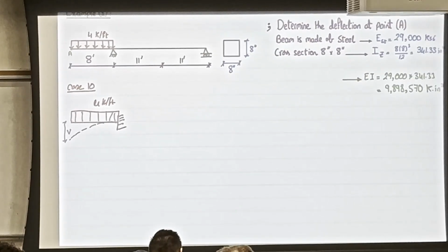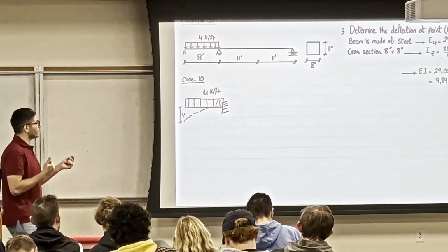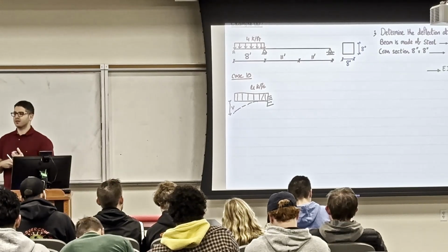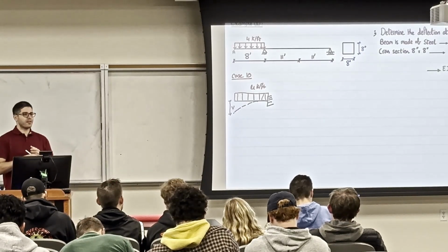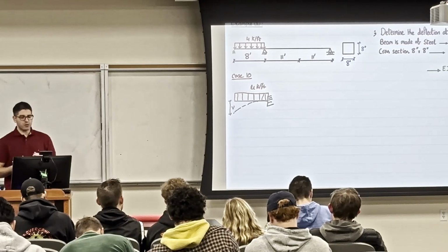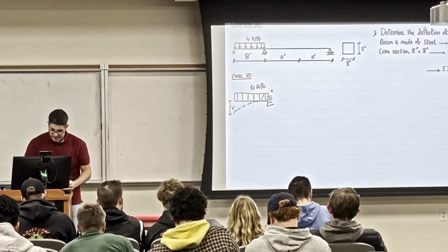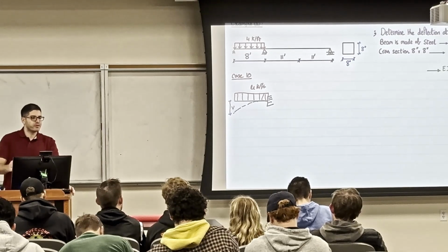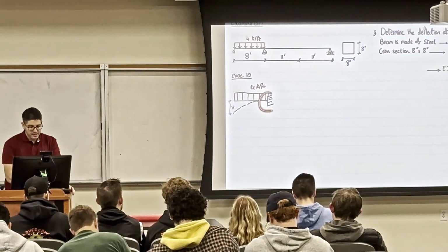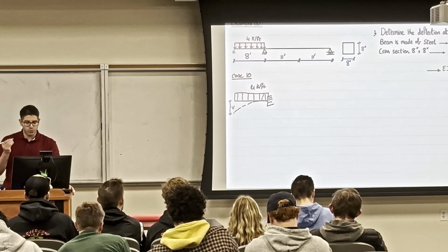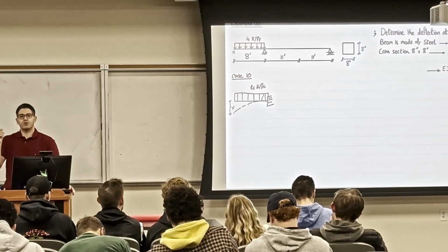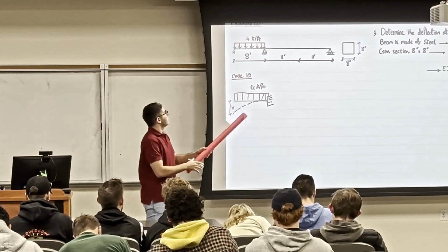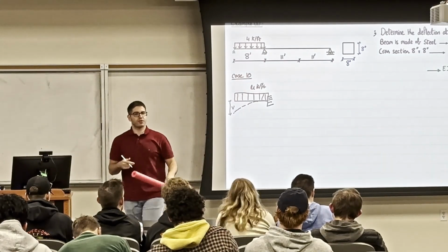But here comes the question. Is this assumption right? What did I assume wrong? That there is a fixed point. And what is the fixed point? What is the difference between the fixation and the hinge here that was originally in the question? Moment. So what we did here, our assumption was we disallowed the rotation when in the real example, we have a roller which allows rotation.